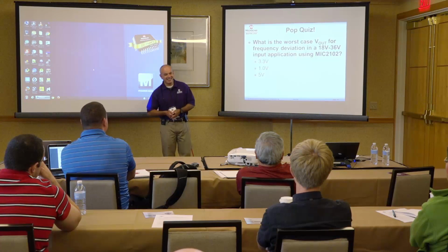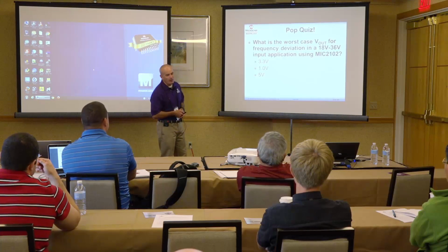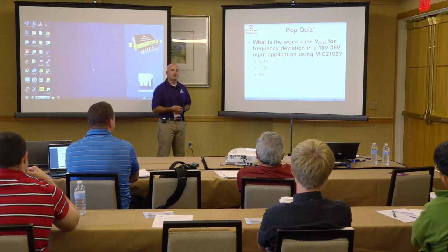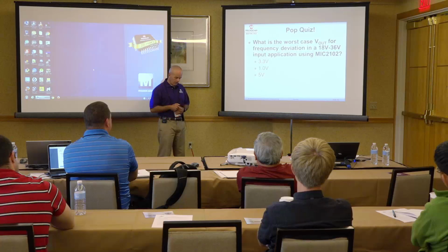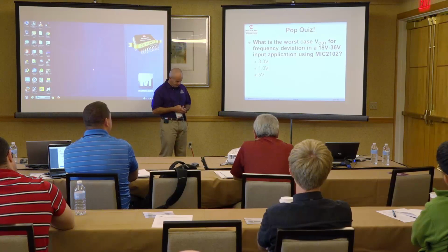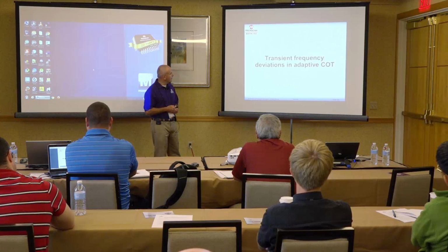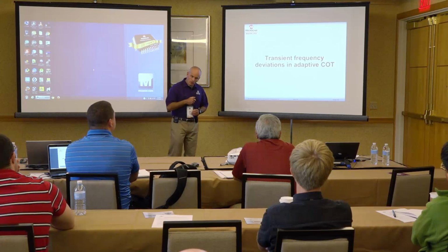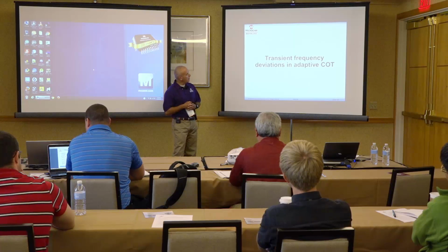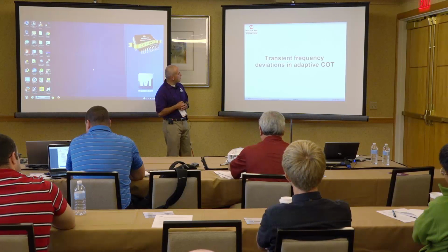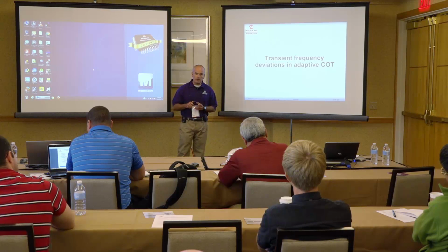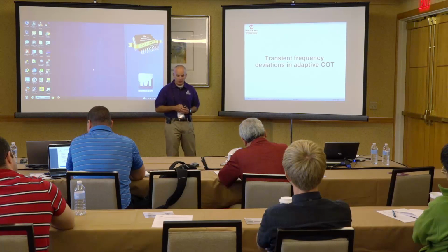One volt, yes. The lowest output voltage setting will be the most sensitive to frequency deviation due to line effects. We want to also look a little bit in further detail about the transient frequency deviation of adaptive constant on time, and to make a couple of additional considerations.